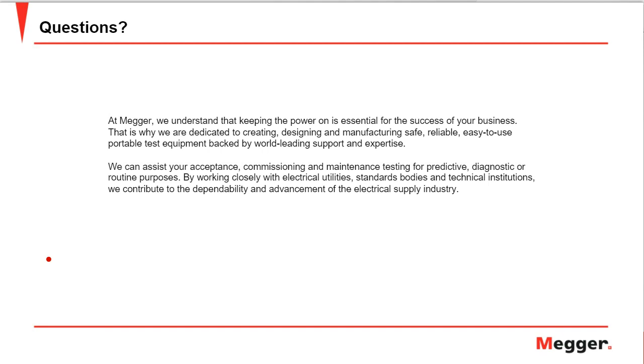Okay, thank you. So the breakers. When we think about the out of step trip function in the protection system, the tripping has to be avoided when the angle between the systems is near 180 degrees. What happens is, if a trip occurs during this condition, it imposes a very high stress on the breaker, and it can cause restrikes and damage the breaker.